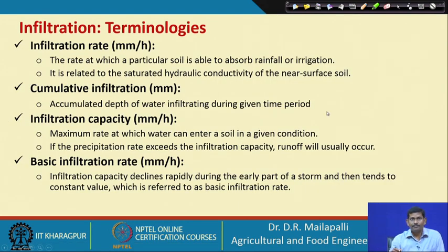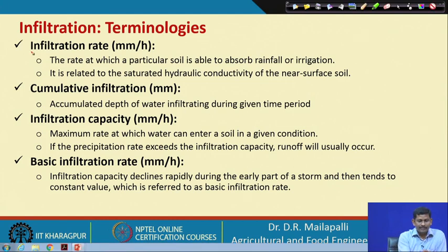And then there are infiltration terminologies. First, there is infiltration rate. It is measured in mm per hour. It is the rate at which a particular soil is able to absorb either rainfall or irrigation water. It is related to the saturated hydraulic conductivity of the near surface soils.